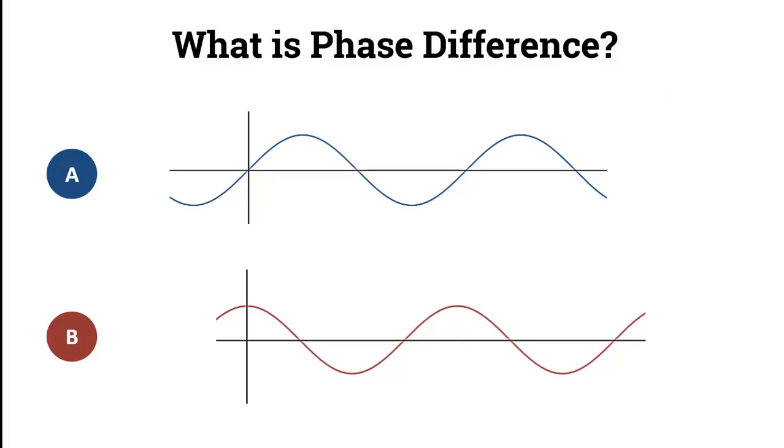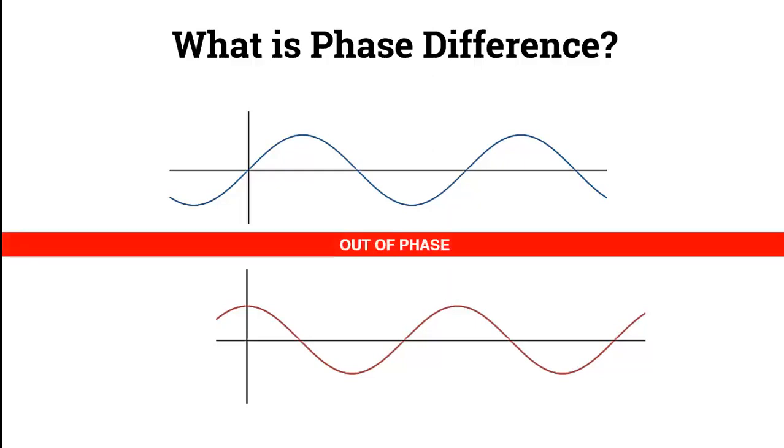So in order to discuss the phase difference, let's take a look at the distance between the two waveforms at particular times. Here I am showing the distance between the two waveforms at time 0, shown with a black straight line, and when we move in time we see that the difference of the distance is not constant, it's varying. The length of the black line is varying, so that is telling us that these two waves are out of phase.